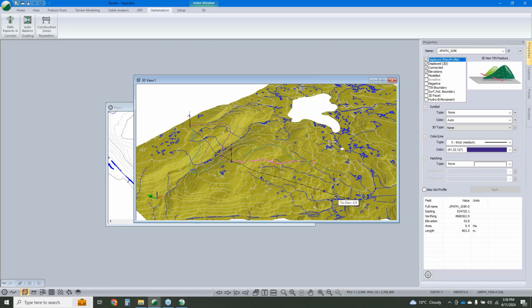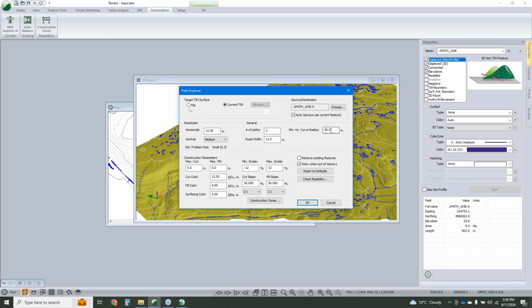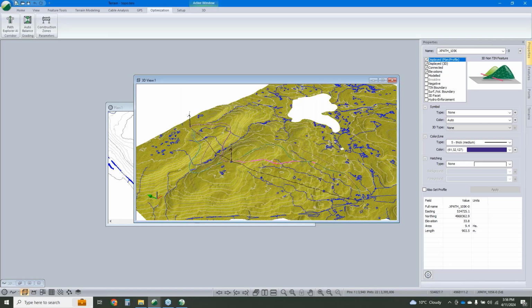Yeah, generally, rule of thumb, less than a quarter of that number. I usually don't go any higher than 20 meters. If it's really complex, gnarly terrain, where there's a lot of detail that I want to account for, I may reduce that. I usually don't end up going any less than 5 meters. But then there's a trade-off.